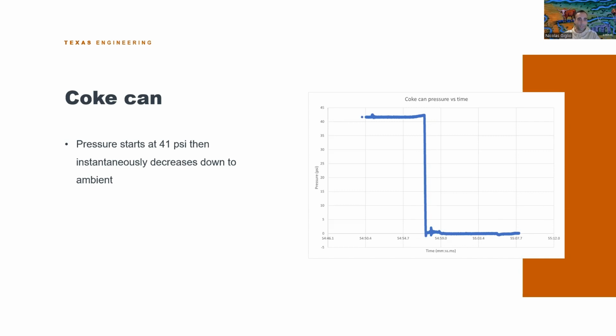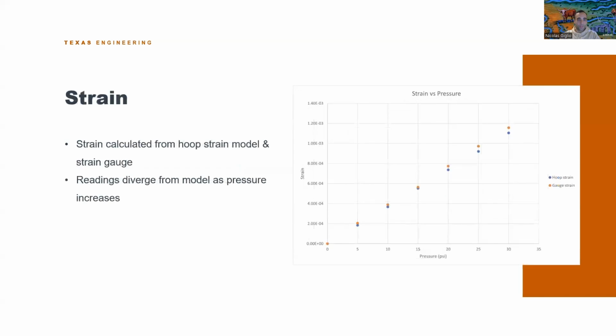I think the conclusion here is that strain gauges are very handy, very accurate, and I trust them. I would say I trust them more than proof strain or than model strain, specifically when using high accuracy systems like National Instruments. Their stuff is really, really quality stuff, and I think it keeps a lot of noise from being introduced into our calculations. And so I do trust the gauge strain a little bit more than I do the calculated models.